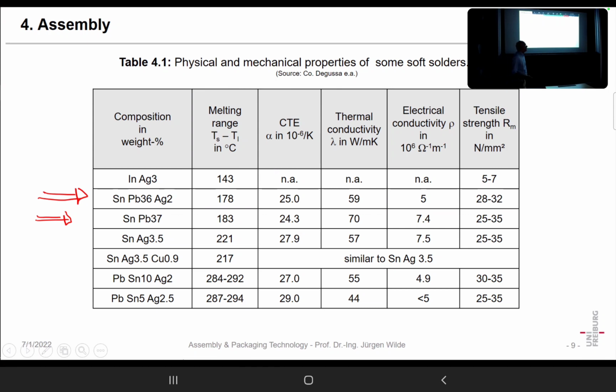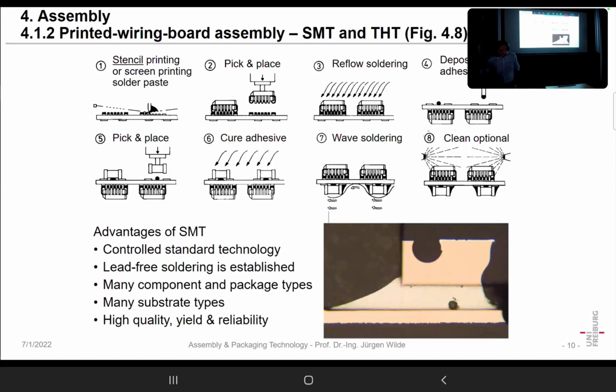Cryoelectronics, for instance, is also used when you have infrared cameras. Yeah, so these are cooled down either with a Peltier cooler or with liquid nitrogen. And here we also often have indium flip chip bumps, for instance, in order to tolerate these stresses at low temperatures. Okay, but now let's come to the